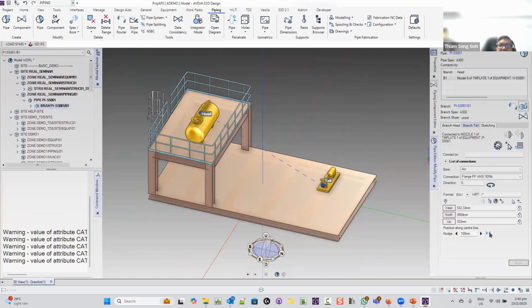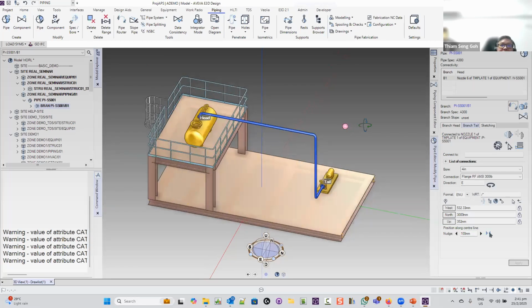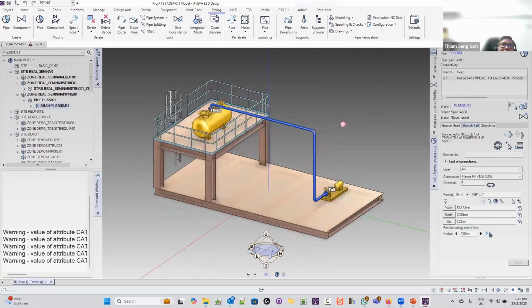With this in mind, you can use automatic routing without any settings if you want to. Let me just do a save work. Every time you save work, you can put a comment as to what you did. And if you don't unclaim, nobody else can take over your job, but you can continue to work on the same items that you have used before. So just do a save work. Then we can click on auto route branch. Yes, you see that it's warning me I have a point crowd. Quite nice, isn't it?